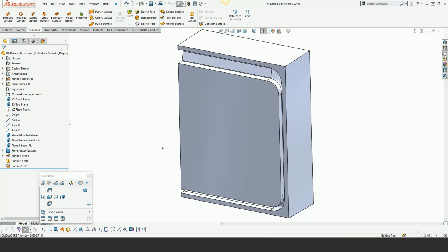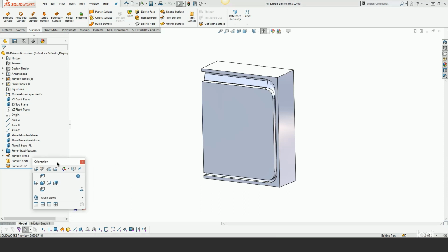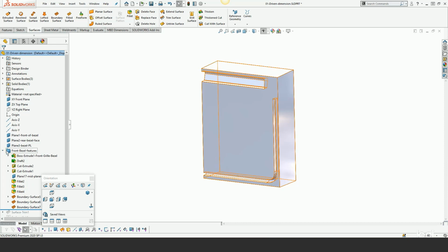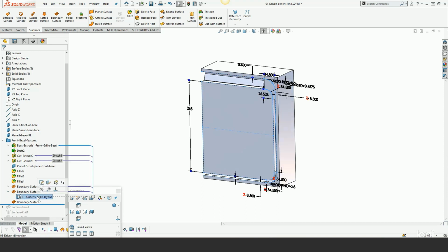An often overlooked feature of SolidWorks is driven dimensions. It's based for me on the fact that in SolidWorks you delete nothing, you change everything. And that's a real benefit, because if you change your mind, you can revert back to previous design intents. So let's use this example of this front bezel with this cut in it, and we're going to roll back to the feature where this cut is created using kind of a driving sketch, this one right here.